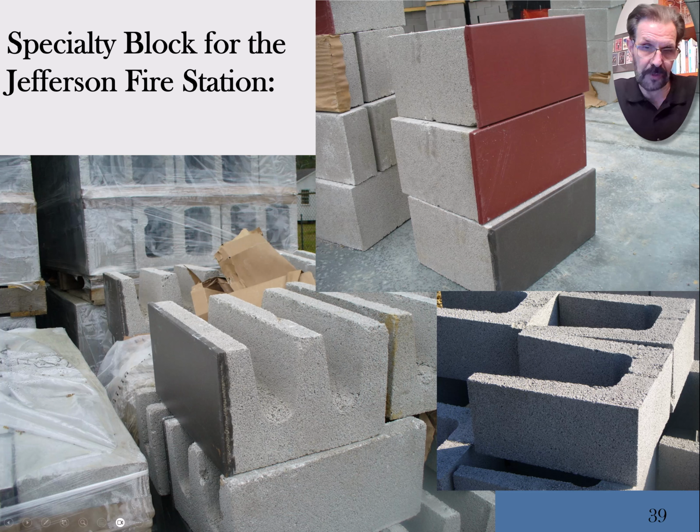The same thing in this picture here. The lower picture, well, my cursor doesn't work in here, but that block on the bottom left is a double wide bond block. So it's got 2 troughs in it that they're going to make into beams. And so that one, I guess, is still 12 inches wide, 12 inches for the depth of it, or the thickness of the wall, basically, where, of course, the ceramic tile is going to be on the exposed side.